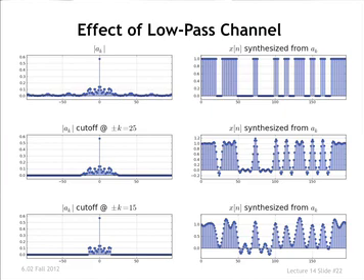If you go even more extreme, here's an even narrower channel. What comes out is even more rounded, because you've taken away more high-frequency components. The signal just can't wiggle that fast. It takes its leisurely time going through its paces here, and you can imagine that you can be thrown off when you try and take samples.